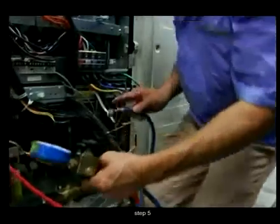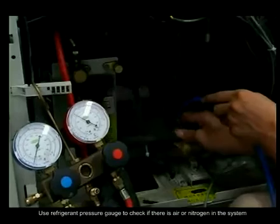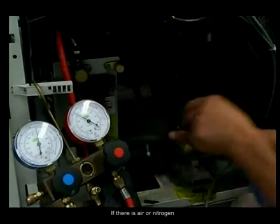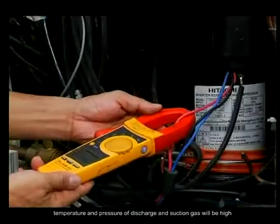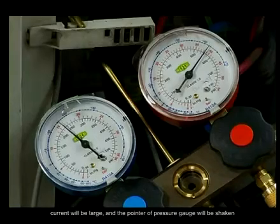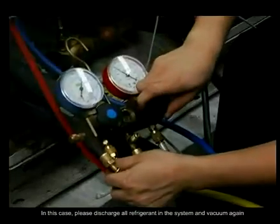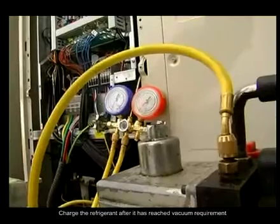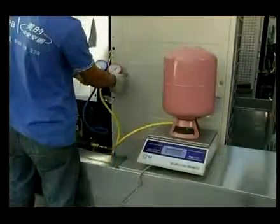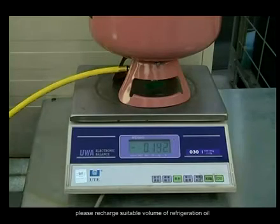Step 5. Use a refrigerant pressure gauge to check if there is air or nitrogen in the system. If there is air or nitrogen, the temperature and pressure of discharge and suction gas will be high, current will be large, and the pointer of the pressure gauge will shake. In this case, please discharge all refrigerant in the system and vacuum again. Recharge the refrigerant after it has reached the vacuum requirement. If refrigeration oil goes out during the process, please recharge a suitable volume of refrigeration oil.